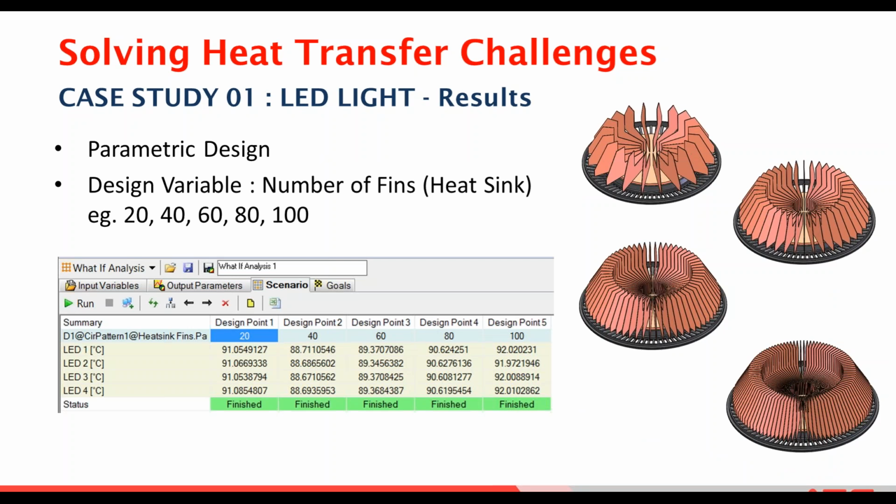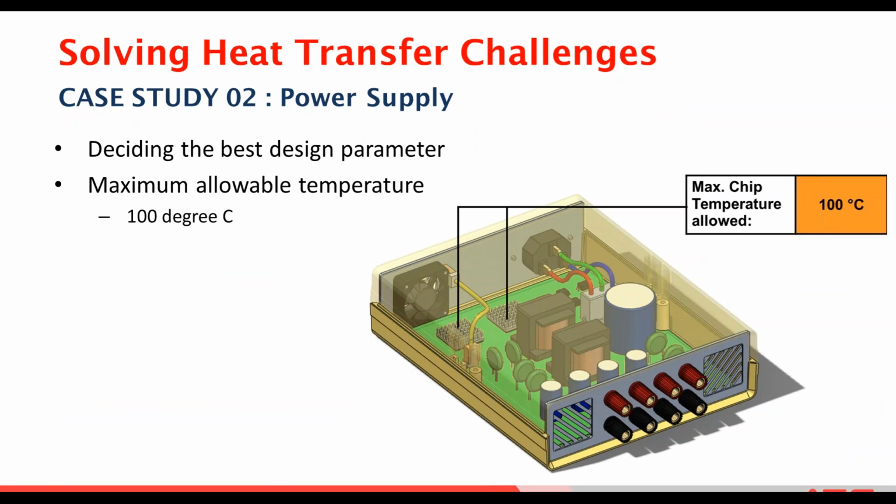We understand that more fins doesn't mean the heat is dissipated more effectively. From these studies, we understand that the best design here is actually 40 fins.